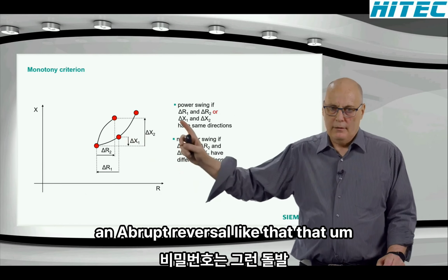Over here, the voltage just stops. Obviously, the voltage does not continue with its trajectory, it stops. And you can see the pickup of the C phase zone 1. Okay, in this model, the tripping was not done to the breaker. Otherwise, the current would have stopped. There would have been a single pole dead time here, but unfortunately the model used at that time did not really trip the breaker. It was to show the zone 1 trip would have come, and on the other phases, the power swing blocking stays on over here. That is clear.